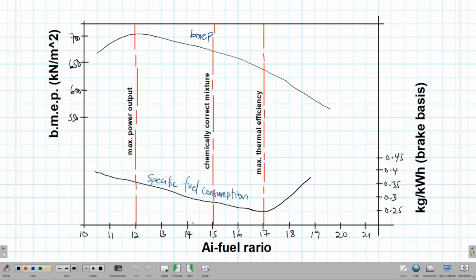When a very weak mixture is employed, the rate of spread of the flame is relatively slow and may even continue throughout both the power and exhaust strokes. This may cause the fresh charge to ignite during the next induction stroke, resulting in backfiring or popping back through the carburetor. That's for old systems.